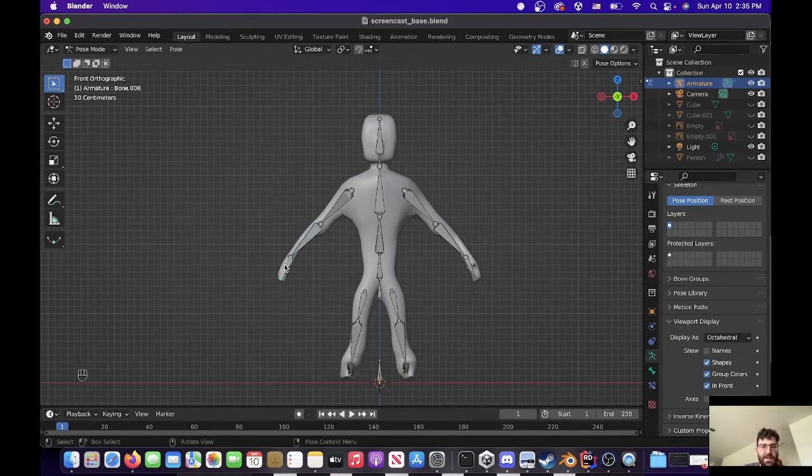If we want to move this hand all the way up here, we can't. So that's where inverse kinematics can be useful. We're gonna do the very abbreviated version. These are rig bones, which correspond to actual parts of the body. Now we're gonna make things called control bones, and those can be used for positioning rig bones. So the only bone they're gonna be parented to is the root.